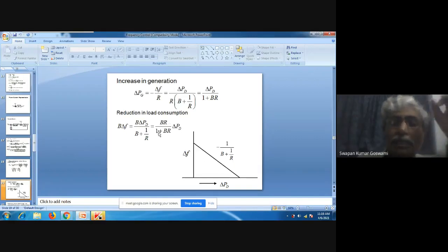So you can see that this reduction in power demand now can be utilized by the new load. So the new load will now be getting this much of power. At the same time, the new load will be getting this much of power output from the generator. As a result, how much is the total supply of power to the newly connected demand of delta Pd? If you add these two up, it will be equal to delta Pd. So that is how, perhaps, this explains how the newly connected load is being supplied by the system when a new steady state is reached.